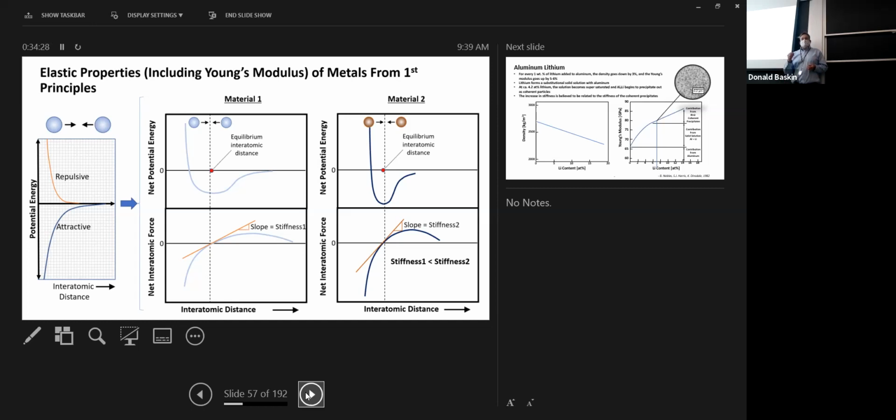So how do you get to that stiffness? You don't have the tool just to say, okay, well, we'll use stainless steel. That'll make it stiffer. That doesn't really work, because this stainless steel is the same stiffness as the low carbon steel. By the way, you'll find in industry when you go out there, not a lot of engineers know this, that you can't really tweak stiffness.